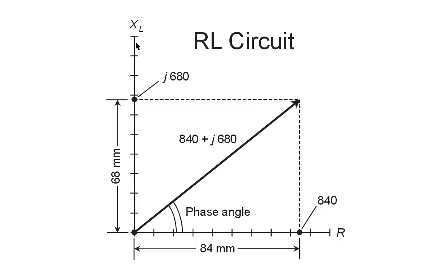other. We can plot situations like that on a quarter plane graph with resistance on the horizontal axis in real number values and inductive reactance going up on a vertical axis in imaginary number values. That's what this J operator is all about. What we're looking at here is figure 3-9. If you have the printed book, you'll be able to find it on page 76. It's back in chapter 3, of course, where we discuss the way that resistances and inductances in series combine.